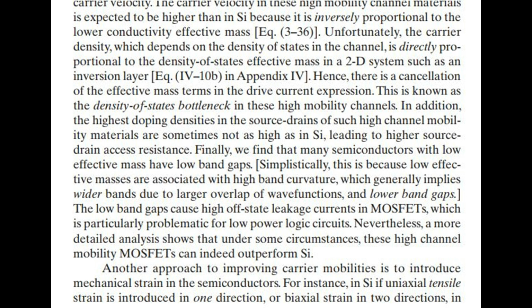The low band gaps cause high off-state leakage currents in metal oxide semiconductor field effect transistors, which is particularly problematic for low-power logic circuits. Nevertheless, a more detailed analysis shows that under some circumstances, these high-channel mobility metal oxide semiconductor field effect transistors can indeed outperform Si.